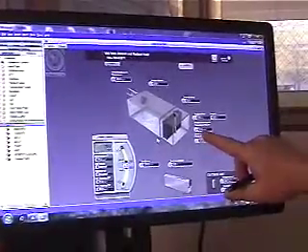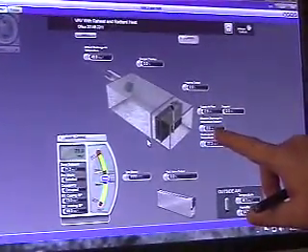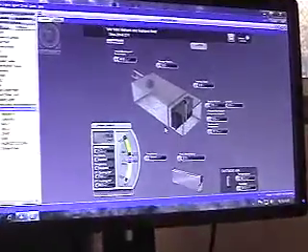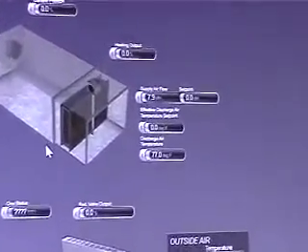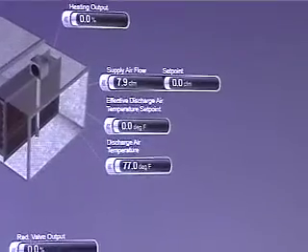Heating's a little bit different. The box goes into heating mode, so when we go below set point, the first thing it's going to do is try to open up the heating valve to maintain a discharge air set point. Right now it's reading 0 because it's satisfied, but when it actually goes to heating mode, it'll reset, I believe, between 55 and 85 degrees. Your first stage of heating is we start modulating this heating valve to maintain a discharge air set point. Once that PID gets up to over 50% and we're still below set point, we then reset the airflow set point between the heating min and the heating max.